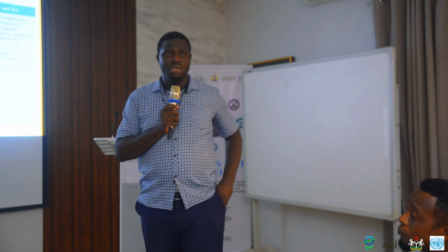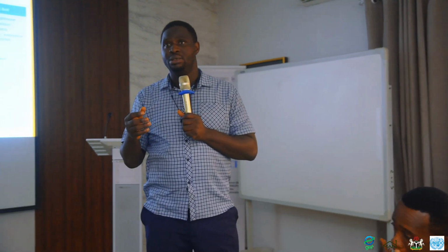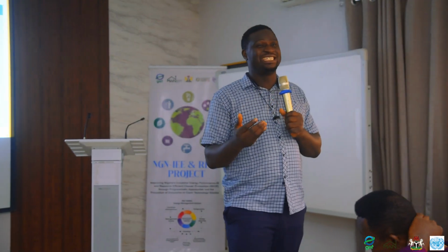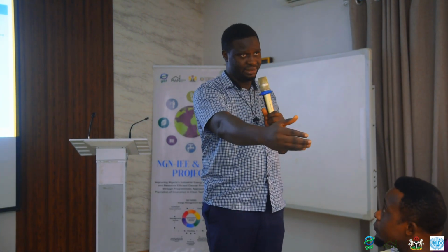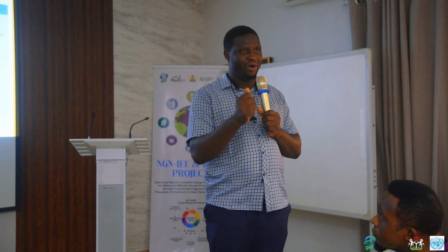I would say when you talk about significant energy use, as for a bulb, it depends. Some irons are 2,500 watts. If you have 3 bulbs that are 10 watts, on for how many hours? Let's say 24 hours in a day. Okay, for 16 hours. If we multiply the 30 watts by the 16, I think we have something like 480 watt-hours.